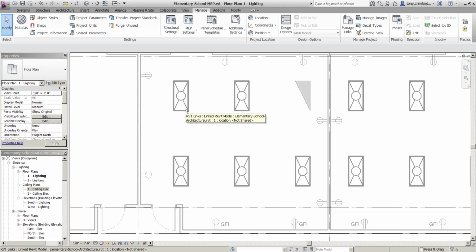So it looks the same to you, and has no effect in the original file, but when an MEP links it in and does this batch copy, anything that's been rotated 180 will be flipped. Say you inserted from drawing a wall from left to right versus right to left, or on the bottom left corner or the top right corner, and then maybe rotated it. In the MEP file, the ones that have been rotated will come in off by 4 feet. So it doesn't show in your file, but it will affect the files downstream.